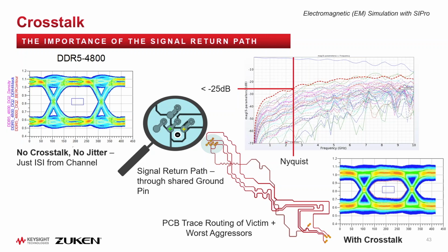Finally, we can see that even with minus 25 dB of near-end crosstalk, far-end crosstalk, it still adds a significant amount of eye reduction. In this case, it was about 37% of voltage margin reduction, and also it does impact the timing margin to a smaller amount as well.